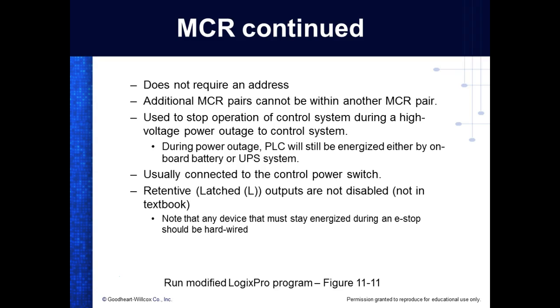Usually connected to the power switch. This is what we've got to understand. Retentive or latched outputs are not disabled. The book does not tell you that. Note that any device that must stay energized during an E-stop should be what? Hardwired. And we've got a program out there we'll run. But let me show y'all an actual E-stop circuit.